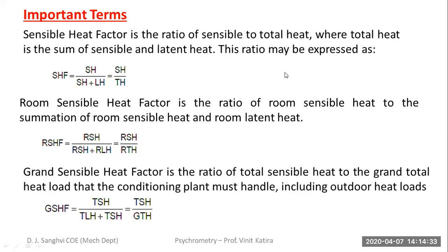So for larger applications such as your hotel rooms or your office spaces which has got multiple cabins, meeting rooms, etc. In such situations, the occupancy is for a large amount of time. So there also, to maintain the work efficiency, there should be some kind of recirculation so that fresh air can enter.